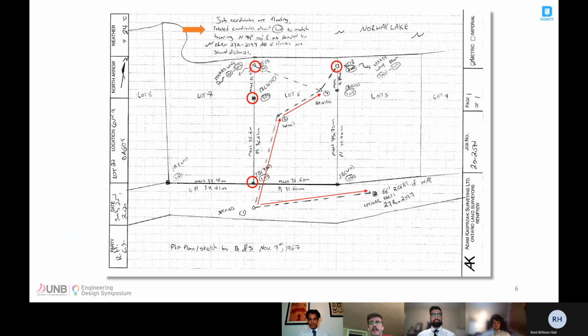A quick sentence is jotted down at the top to describe the coordinate system, if any, that the data is in. Comparisons of distance and measurements, distances measured, and measurements from previous surveys can quickly be shown on the field notes. Lastly, the plans referenced to conduct this survey can be listed, allowing other surveyors or draftspersons to quickly review previous survey plans. All of these features and highlights are aspects that a digital field note application should be capable of at the bare minimum.